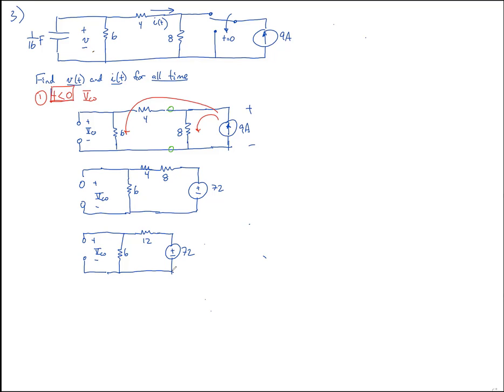All right, now, can I add these two resistors because they're in series? No, because we're still going to destroy that VC naught. So do you want to do another source transform? Can't you just do a voltage divider? Bingo. So you could, if you wanted to, continue to source transform. And that would put these two things in parallel, which could simplify. You could, if you wanted to, do a mesh. Now there's just one mesh. You could, if you wanted to, do a nodal. You just got one nodal. But instead of doing any of those things, I'd recognize this is just a simple voltage divider.